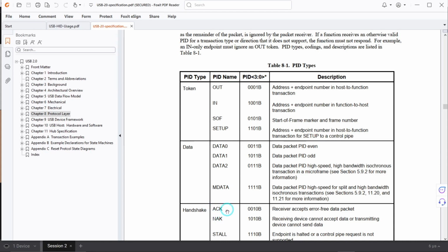And I have already seen that some of these keyboards respond in different ways. I've got an El Cheapo Lenovo keyboard over there that doesn't seem to be coming back with NACKs, which it should do, but it comes back with a report. It says ACK and a report in which all the keys are 0, all the scan codes. So in other words, there is nothing to report, and it does that. I don't know why.